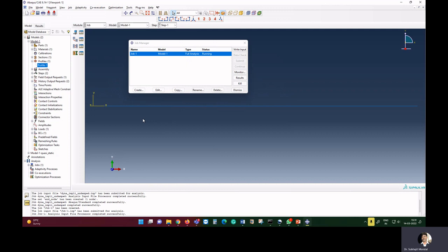Since the system is undamped, there will not be any transient part. In the next run, we are going to introduce damping so that we can get the transient as well as the steady state response. Whatever response we get here is the steady state response corresponding to the instantaneous loading.